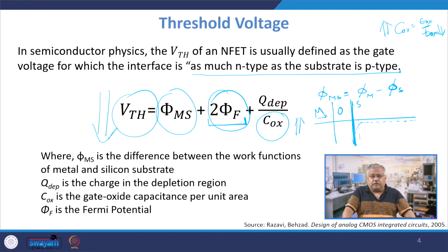This is known as tunneling, and this is leakage current. So, your leakage current will increase, your power will increase. So, the cost you pay for a lower threshold is a higher power. So, these are a few very early design knobs with you as a designer to take care of a reduced threshold voltage.